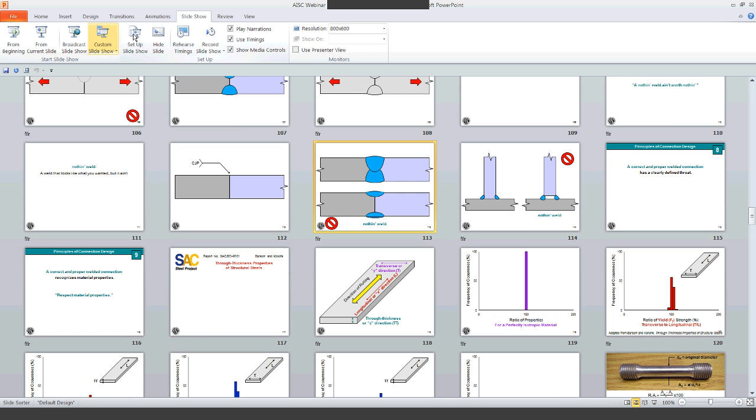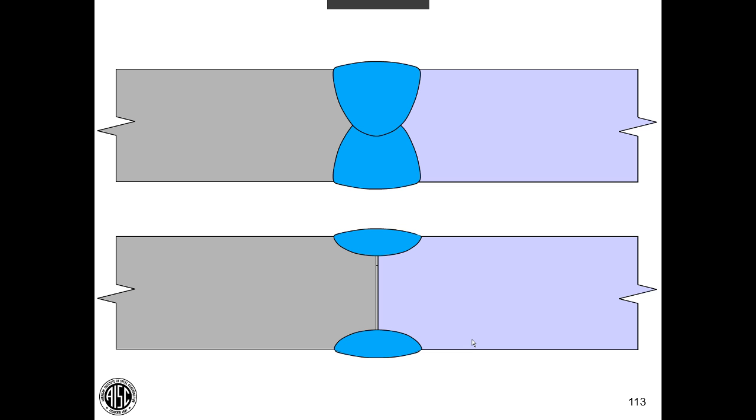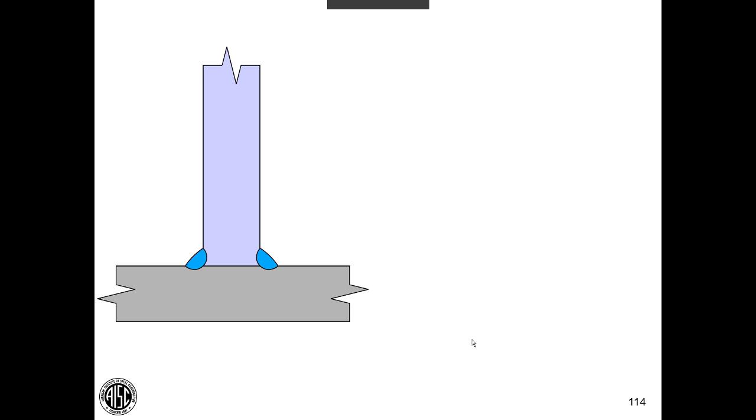So in the top slide, we would have a weld that's made with a pre-qualified detail. The bottom weld, that would not be a pre-qualified detail for thick steel. Now, it is possible to qualify the welding procedure by test. We're going outside the code when we do that. Sticking with pre-qualified details helps avoid that example of the nothing weld. The questioner had it right.